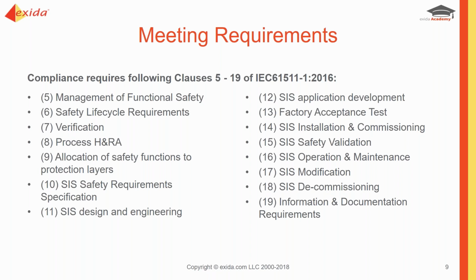Clause 16 covers the operation and maintenance. And as I've said, this is where we'll be spending 90% or more of our time during the SIS normal life. Clause 17 covers modification. And so we have to talk about how we're going to control modification. The management of change is very important. And then clause 18 in terms of the decommissioning. Once we're getting to the end of the life of the SIS, how are we going to decommission? And then clause 19 covers the information and documentation requirements. So to be compliant, we have to meet these clauses.